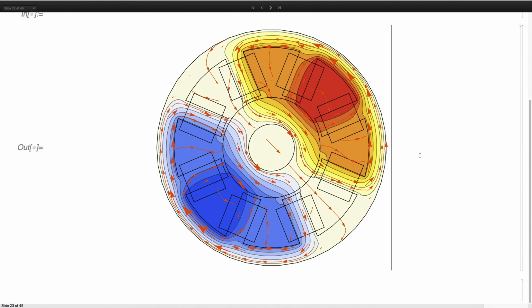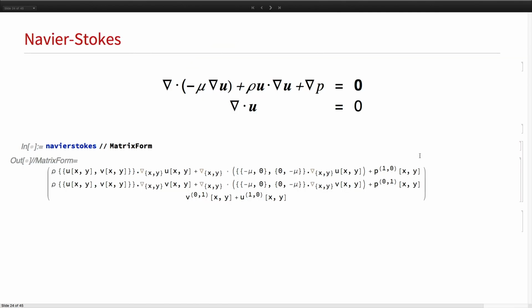All right. So the Navier-Stokes equation. This is a Navier-Stokes equation in the stationary case. The special thing about the Navier-Stokes equation is that the first equation is a vector-valued equation. In the first equation, the pressure P is only available in a gradient form, and P is not present in the second part of the equation. So yeah, that makes it hard to solve.